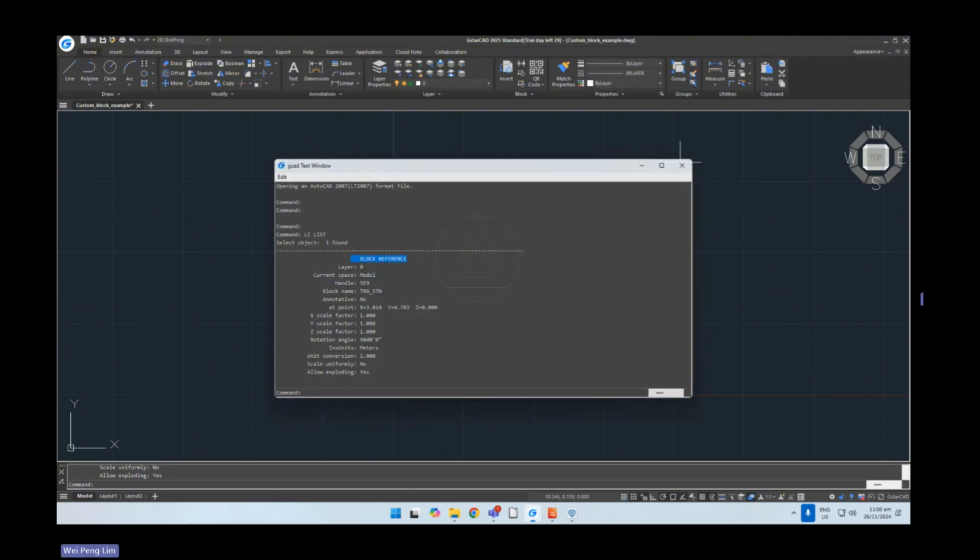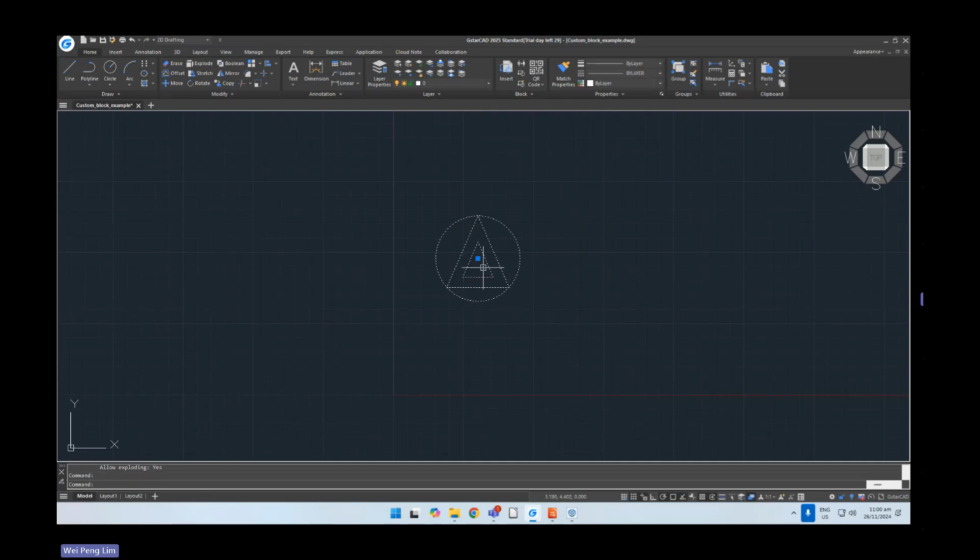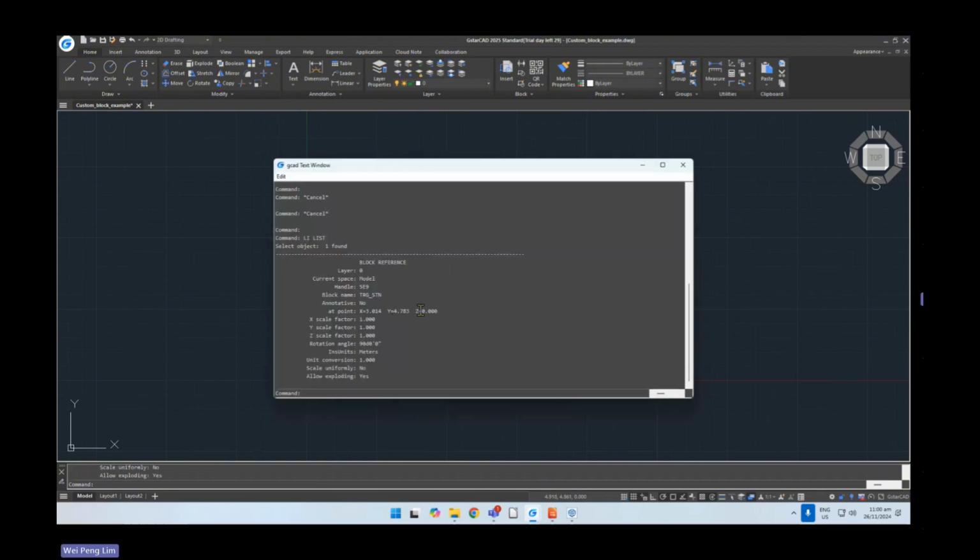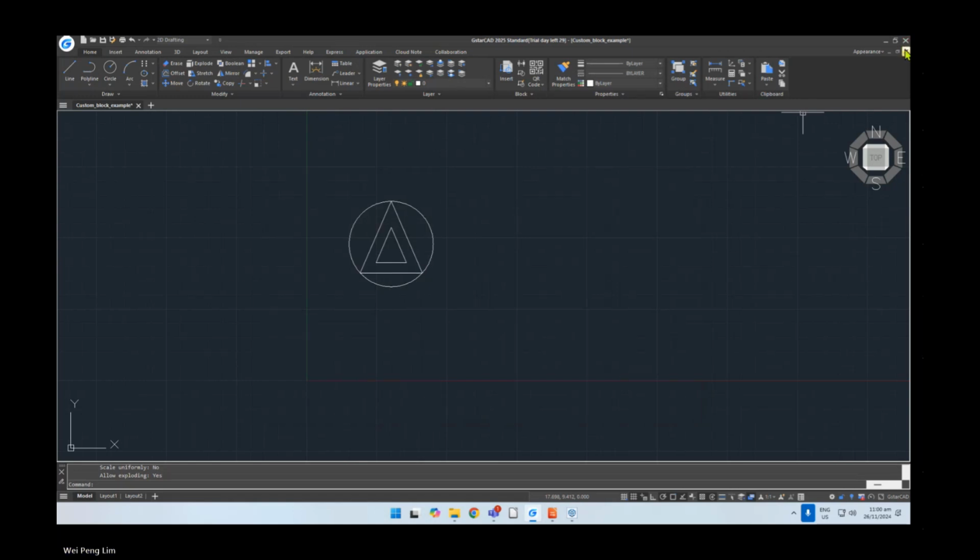Okay. You need to specify the insert point as where you want. In this case, I put a center, this is insert point, and then you say this drawing file. So this drawing file has a block inside like this. You can create multiple different symbols and then define everything as blocks. And each block has its own block name. So this block name is called ERG underscore station, for example. So I want to add this into my feature code library. So how do I do that? So let me show you.